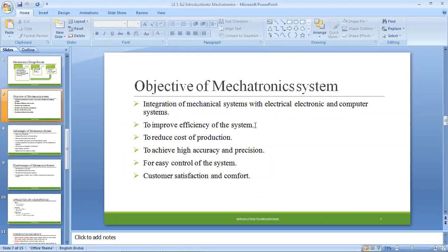The machine needs to be switched on, and later the tool needs to be fixed, and so on. The object needs to be fixed in the chuck, you place the tool in the tool holder, rotate the armature, and bring it into contact with the workpiece. Physical operations are involved. There will be a program for performing all these tasks. The tool will automatically change, with the automatic tool changer, ATC, using a program.